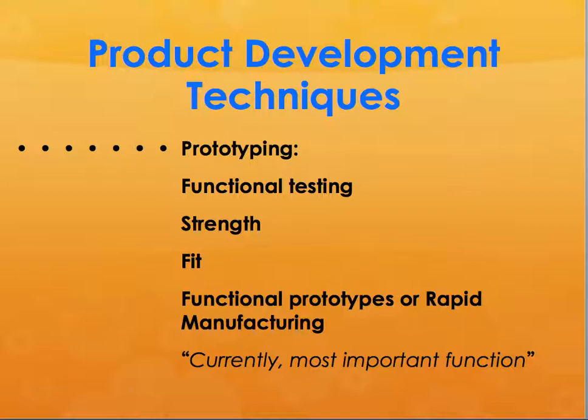The ultimate goal for any of these is to look at the part function in actual service. So functional testing. You want to put it into actual function and see how many cycles it can run, how much strength it has, whether it meets the standards that you have, whether it meets your design criteria and so on.